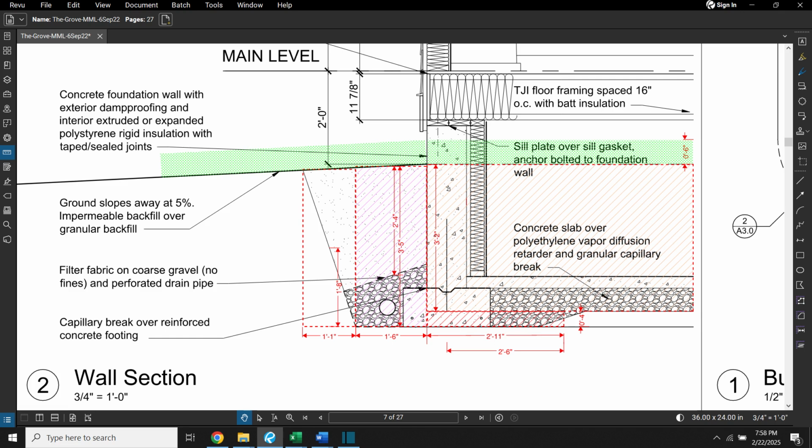The corresponding rectangle starts at the building boundary and extends to the middle of the triangular section on the right. Its height is 4 inches and its length is 2 feet and 11 inches. To simplify calculations, estimators often use the midpoint of a triangle, converting it into a more manageable rectangular shape instead of a complex triangular calculation.